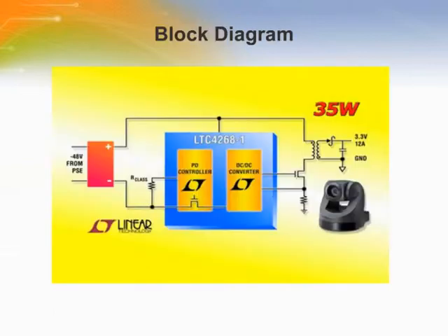The LTC4268-1 interfaces with custom power sourcing equipment using a high-efficiency flyback topology for maximum power delivery without the need for opto-isolator feedback. A feedback amplifier senses the output voltage through the transformer winding during the flyback period and uses this voltage to tightly regulate the output. The transformer isolates the load from the input supply and provides feedback, improving output transient response and overall reliability.